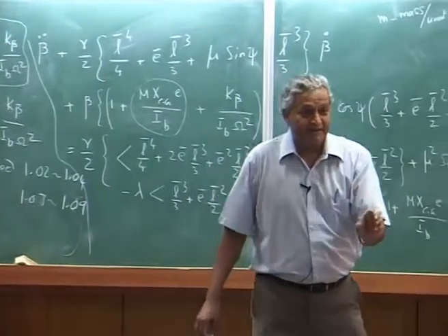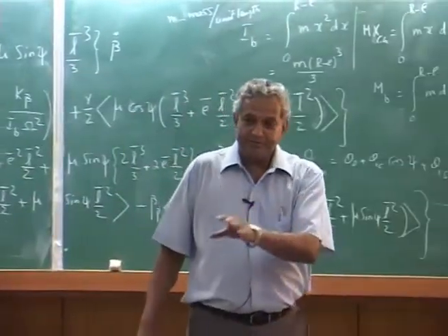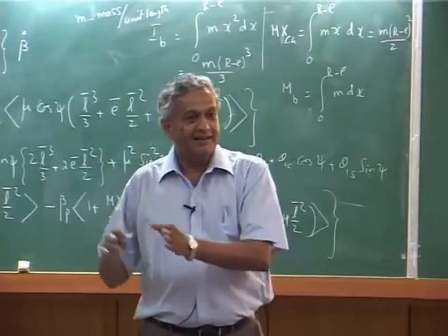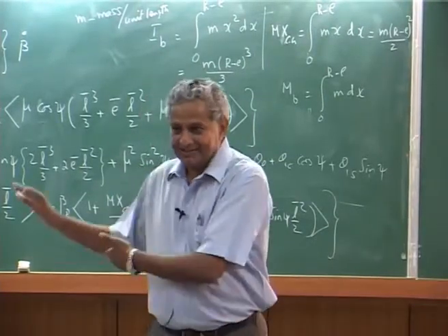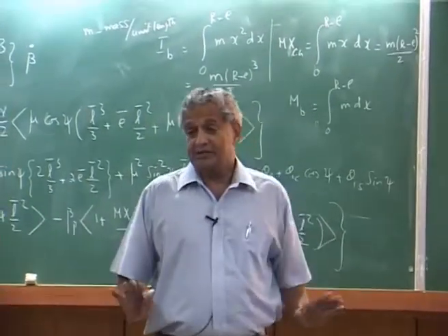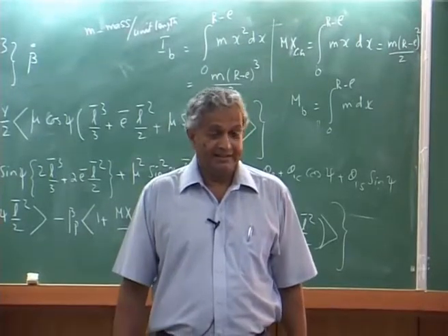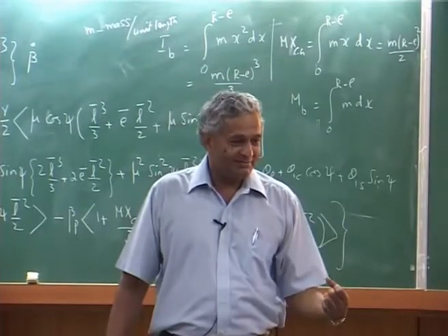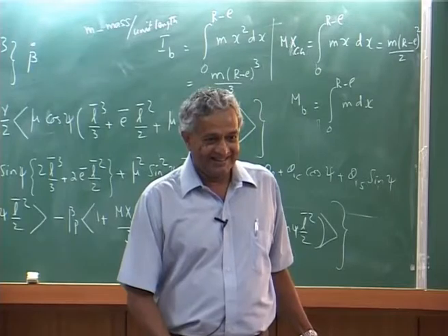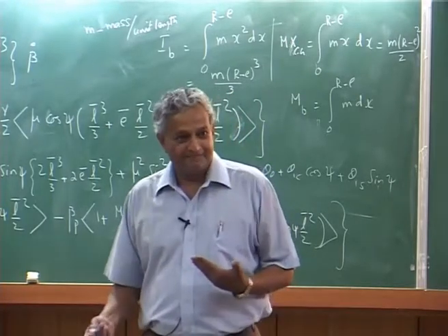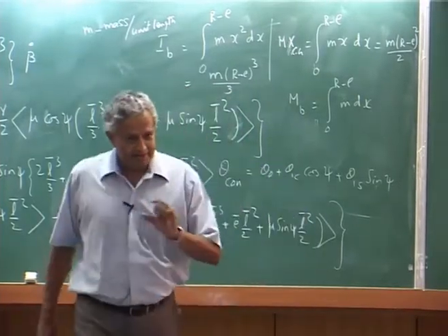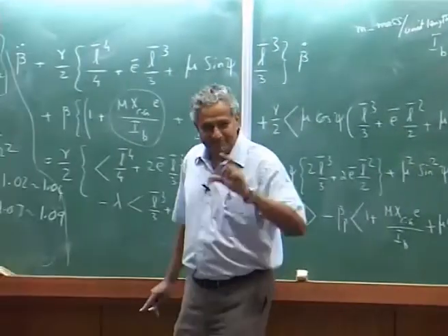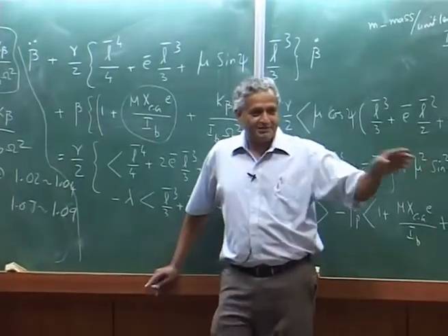So, you will find the problem will be, if it is hingeless, your vibratory loads also are higher. So, you get a control moment high, but your vibration is also high. Now, what is the choice? So, this is where every parameter, everything, there is a plus point, there is a minus point.